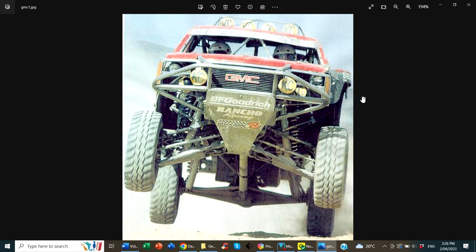But the importance of suspension, it's not comfort. It's not really handling. It's to keep the wheels on the ground. That is what it is for. So in this photo, the suspension has failed to do its job. You could define the job differently, but for the purpose of this discussion, I'm going to say it hasn't done its job. The reason is, while these wheels are in the air, you can't steer, brake, or most importantly for a race car, accelerate.